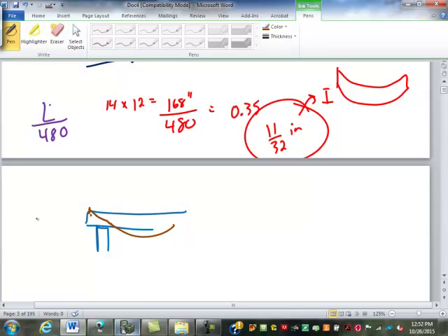If this one also sags and lifts up, you've got a spot here in the middle where it's actually prying your floor sheathing off of the other joist, and then you get really bad squeaks. You can actually have the floor pop free even. So they limit how much you overlap them so you don't have that. I usually don't go any more than 8 inches. Usually less than that if I can.